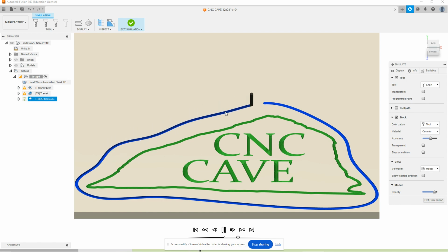If it was going too deep, this is where it would show that it might have one pass instead of three, which I need for my machine because I don't want to cut 3/4 of an inch all at once. My machine is not rigid enough for that, but maybe yours is. So here's where you watch and see what it does.